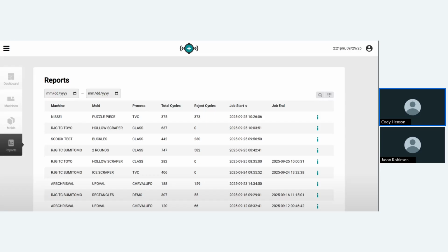Okay, another question was, what would be a different output for warnings? Okay, good question. So for example, a reject, you're gonna wire it to the reversing conveyor that just throws your part away, right? The warning could be wired to a light tree. So maybe when everything's good, it's green. When you want a warning, that tree goes from green to orange to get your attention.